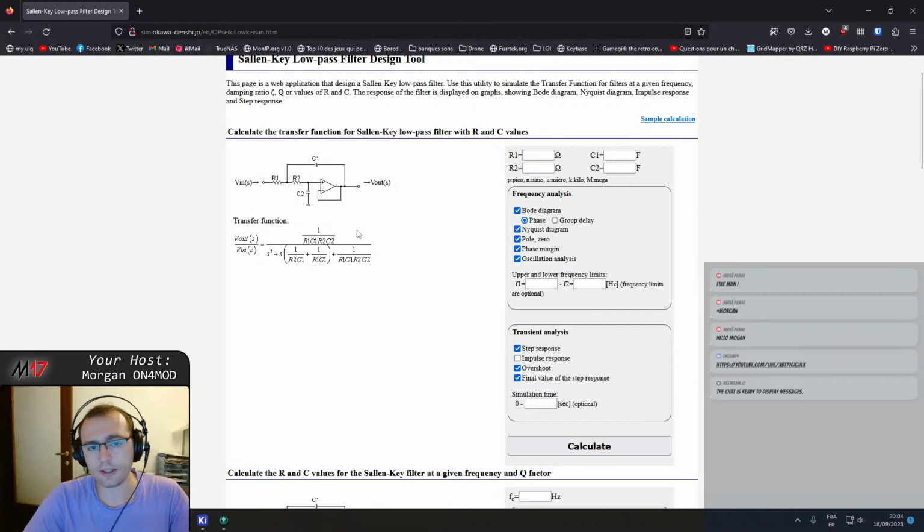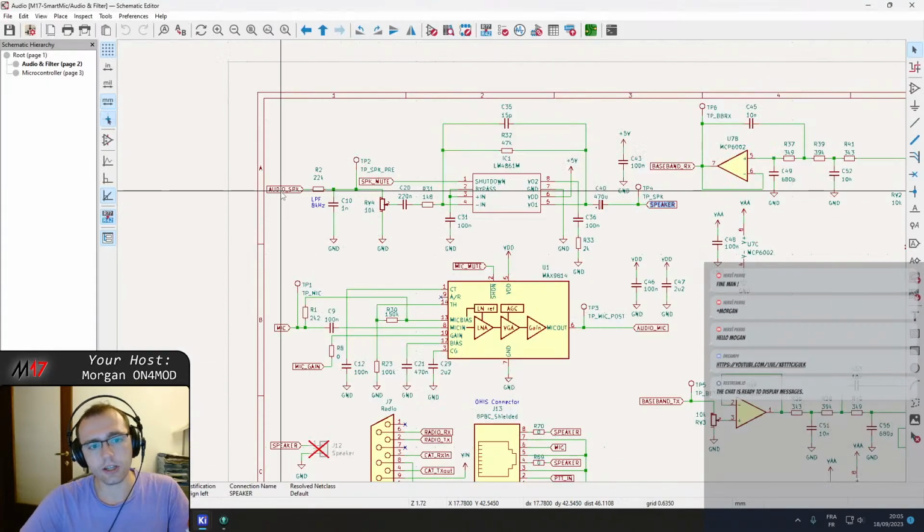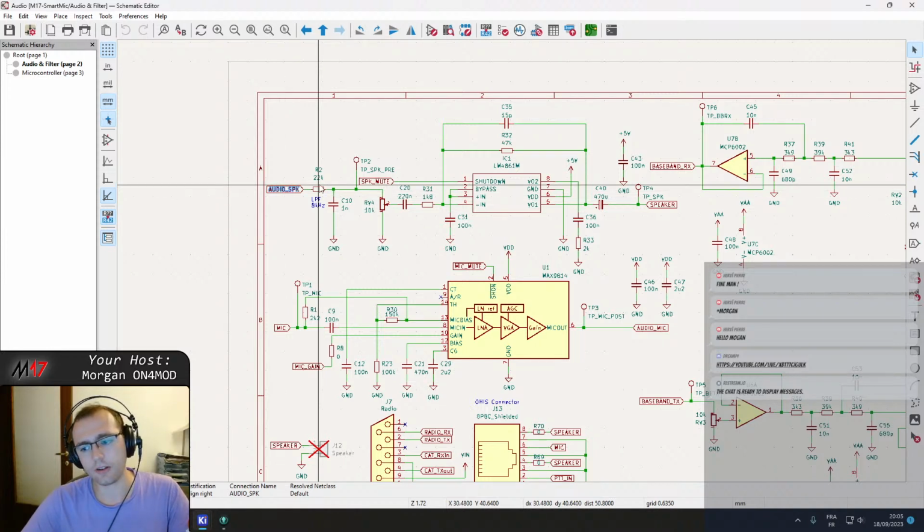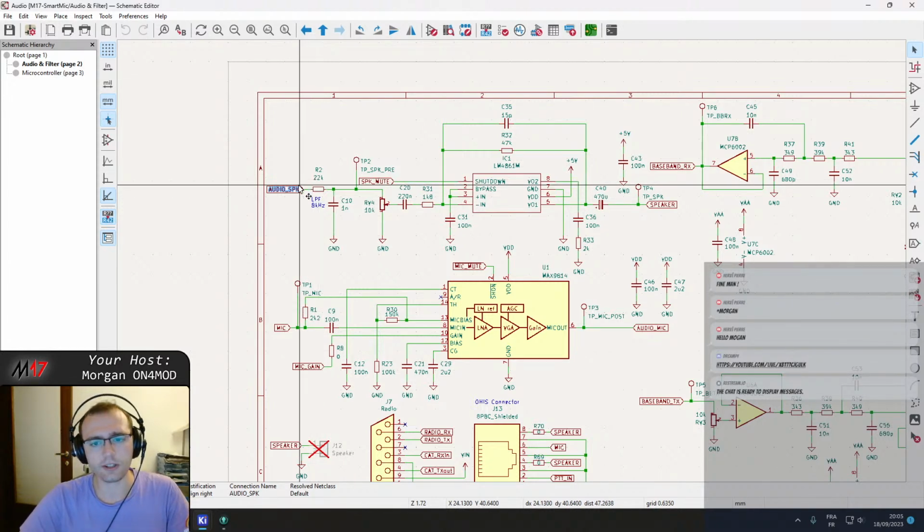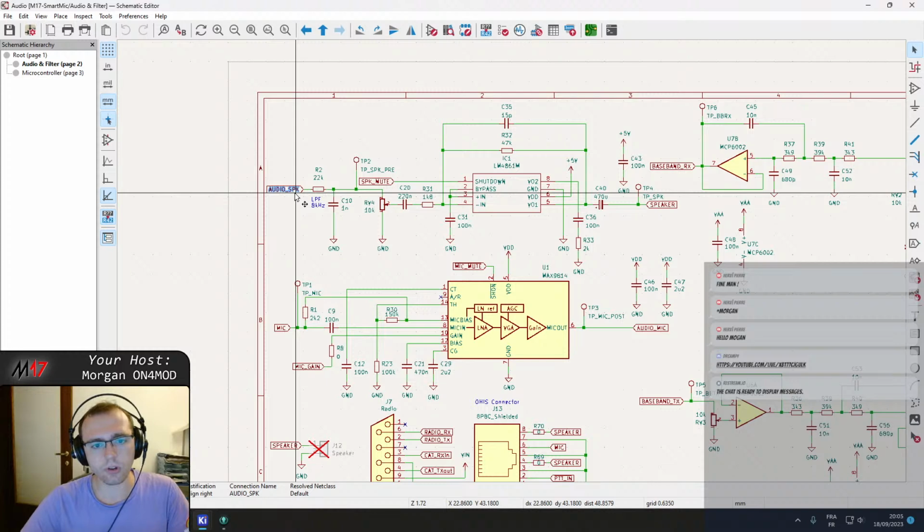Given that we want a gain which we can modify, to have a full range audio output from 0 to 5 volts, so the full power, we'll need at some point to have an amplification, because the output here is at most 3.3 volts, and because of the way Codec 2 is encoded, I've been told that we must consider that this is about 2 volts output.